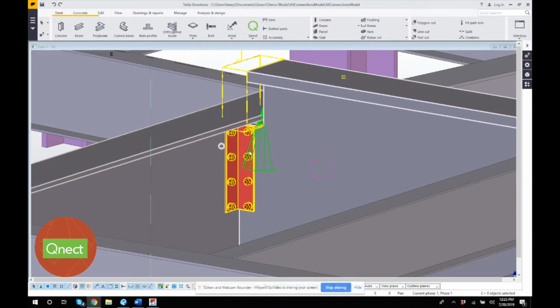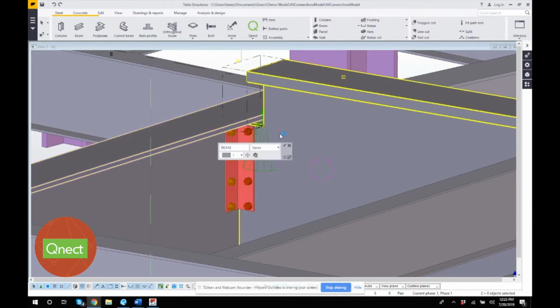As you can see, the vertical bolt spacing has pretty dramatically changed from 3. This looks like probably 5 inches. But in the process, we have saved 33.33% of the bolts. We've met all the limit states. And so we have less bolts to purchase, fewer holes to drill, less bolts to shop install, and certainly less bolts to field install. So we're already starting to see some opportunities and some benefits through the bolt optimization.